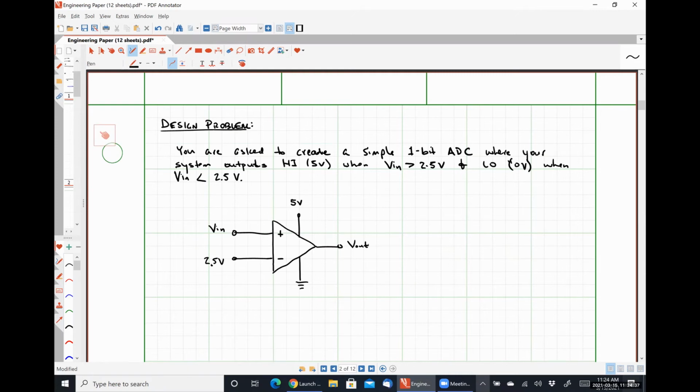So right now, as we have this drawn, we would effectively have to have 2 different DC power supplies, which would be a little bit annoying. But we know enough about simple circuits to figure out how to get 2.5 volts when we have a 5-volt supply, right? What would we do? Just put a simple voltage divider in there. We know that our input impedance should be so large that no current is going to branch off and flow.